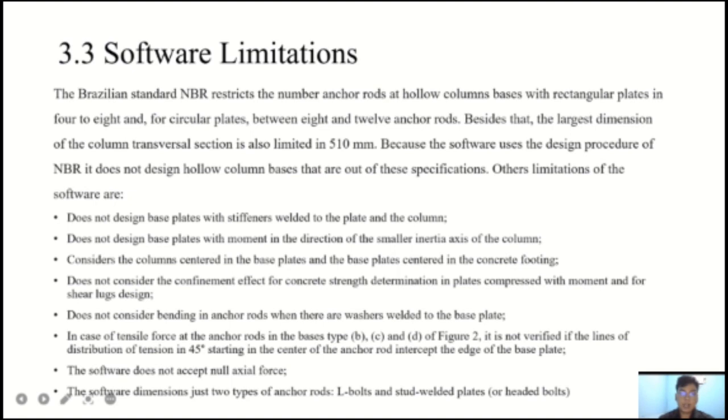Other limitations of this software are: it does not design base plates with stiffeners welded to the plate and the column, and does not design base plates with moment in the direction of the similar inertia axis of the column. It considers the column centered in the base plates and the base plates centered in the concrete footing. It does not consider the confinement effect for the concrete strength determination in plates compressed with moment and for shear lugs design. It does not consider bending in anchor rods when there are washers welded to the base plate.